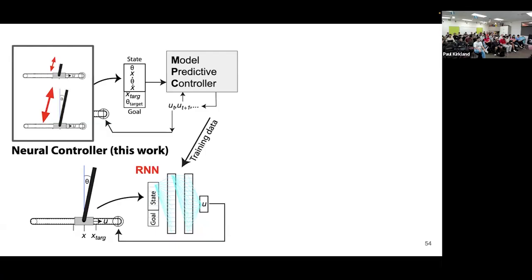It only gets the current state at a time, but thanks to its memory, it remembers the past trajectory and can say, okay, this trajectory must belong to this angle being at this particular offset, and it can adjust the policy to control the carpole without explicitly estimating this angle offset. Okay, this much for this part.